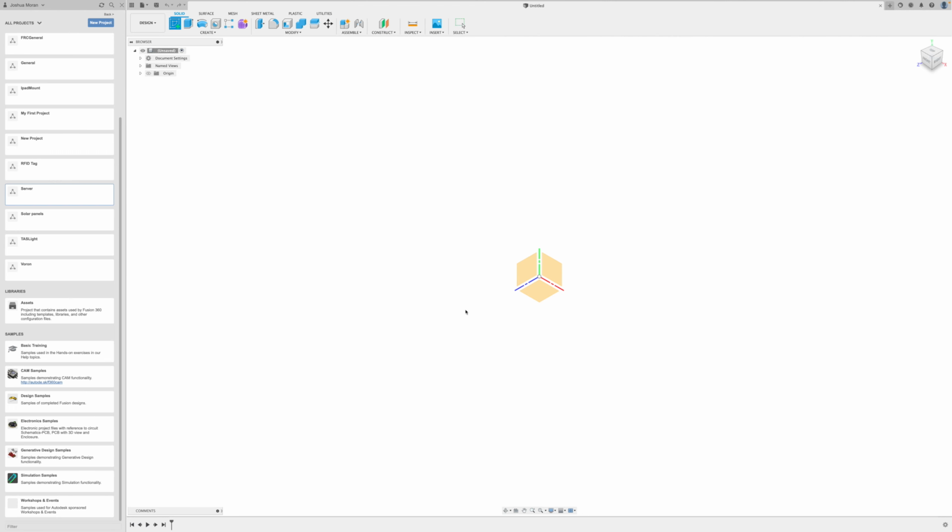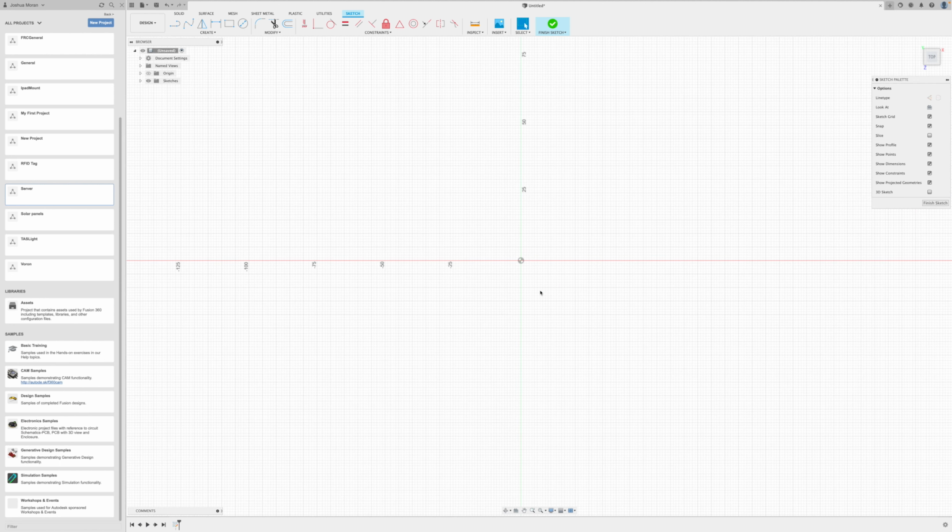So now we see what looks a bit like our view cube that we talked about earlier. And we see 3 yellow squares. These are the 3 planes. So we have the right plane, the front plane, and the top plane. So we want to pick, in this case, the top plane. And it will automatically orient us like this. So now we're the right way up.